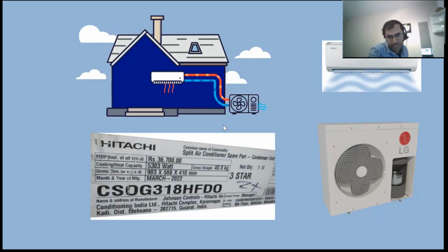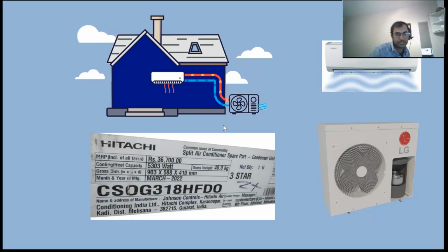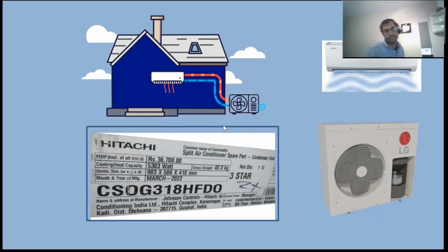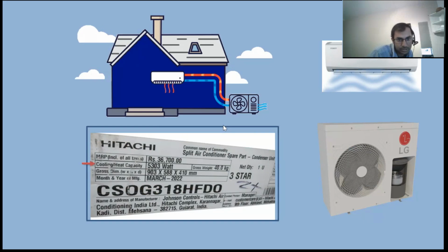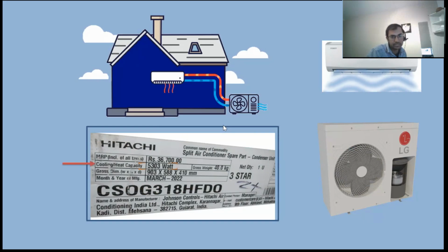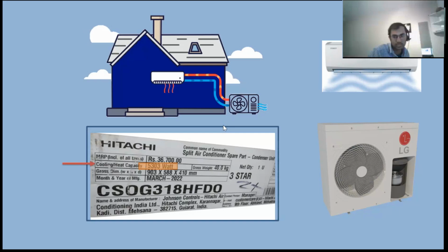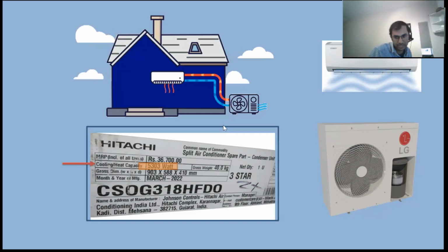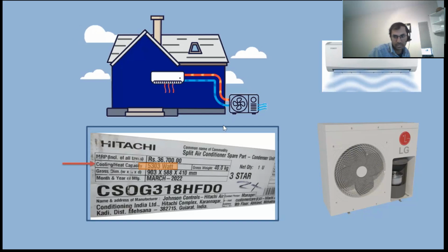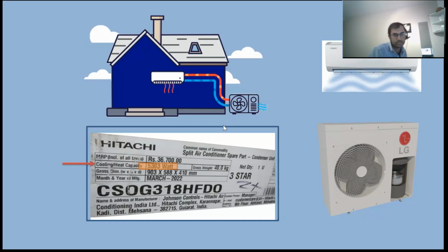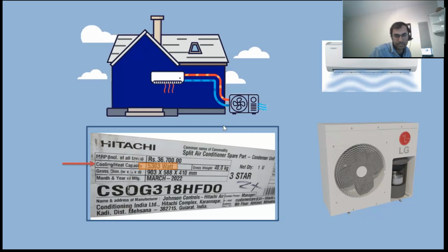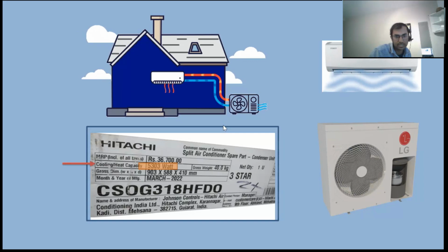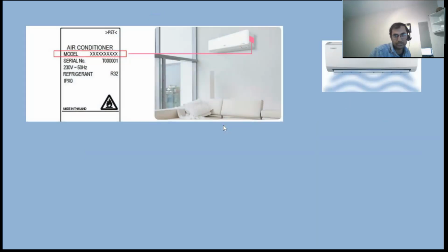Now, if you see the nameplate, it looks like this. On any AC there will be a nameplate with a cooling or heating capacity. It says 5303 watt, which is equivalent to tonnage, just in a different unit. So we try to understand the units used for air conditioning loads, cooling capacity and heating capacity, and how to derive them.